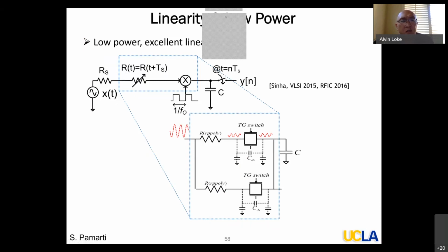So the frequency range is not necessarily constrained to 0 to 1 gigahertz. Let me qualify it. The LO frequency can be higher. Think about it like a mixer-first structure. You have a baseband filter and that's upconverted to the LO frequency, right? A similar thing is happening here. I have a baseband filter, which is very sharp and linear, and I'm upconverting that to the LO frequency. So the LO frequency can be higher. In principle, that does not limit us.